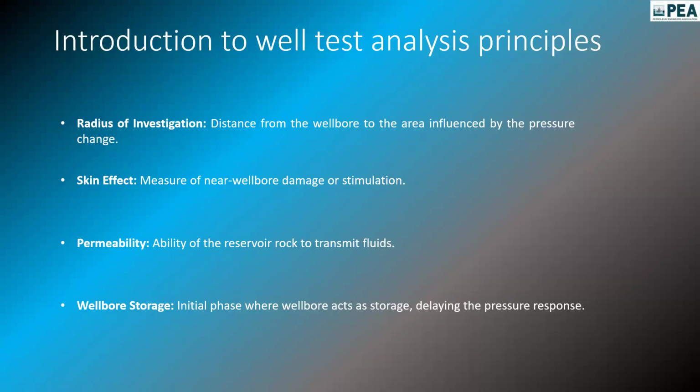But what is the radius of investigation for this? Imagine 8 hours is needed for the pressure disturbance to reach the outer boundary from your wellbore. Here, let us take the time as around 2 or 3 hours after opening the well. The pressure disturbance hasn't reached the boundary, but it would have reached some distance away from the wellbore.